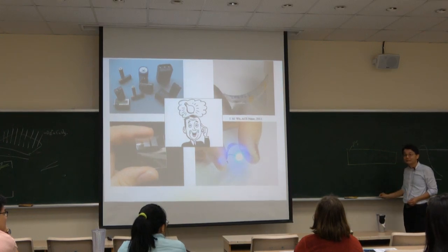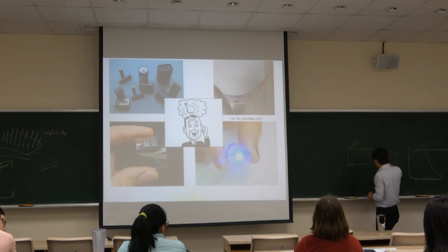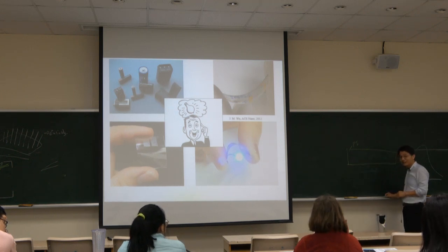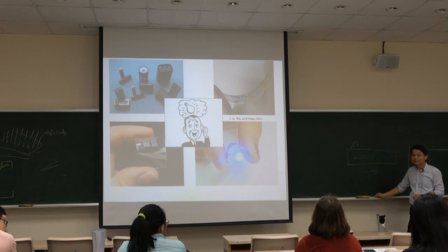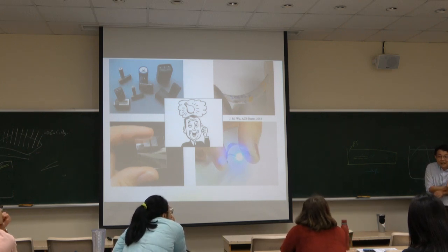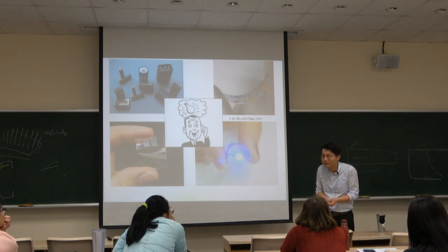Okay? And I will choose one nanowire which is more parallel to this direction, to the x direction. For example, I chose this nanowire, looks like that. And then next, I wanted to apply the contact electrode. For the contact electrode, you have to use silver paste, silver glue. You know the silver glue?